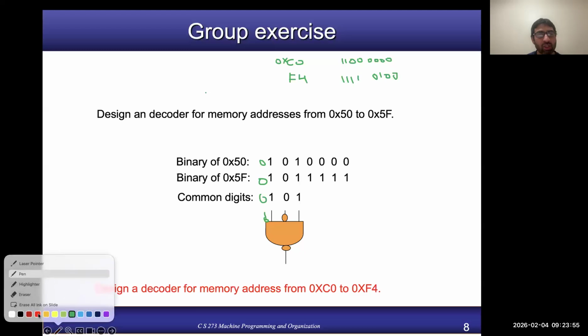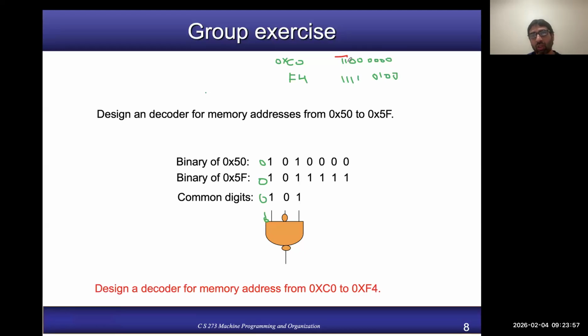The part of the address which is fixed in both cases, which is this one, right? So I simply use a NAND gate with two inputs, A6 and A7, address 6 and address 7, and this is chip select low. Okay. Thank you for letting me know. Okay, let's continue then.